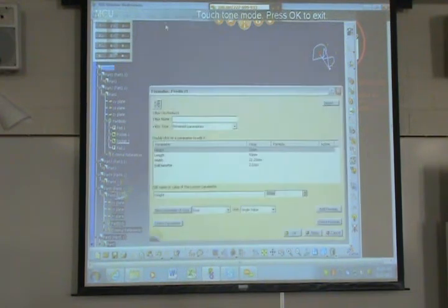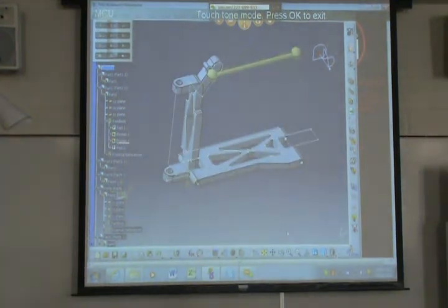So if we go up to Tools and go to Formula and go to Height and maybe make this a little bit bigger, like 35. Let's see if this should work. Yeah. So the height just increased on my part, and now this thing has kind of expanded, keeping all of the relative parameters. They're a consistent ratio, and so I'm able to move this thing up.